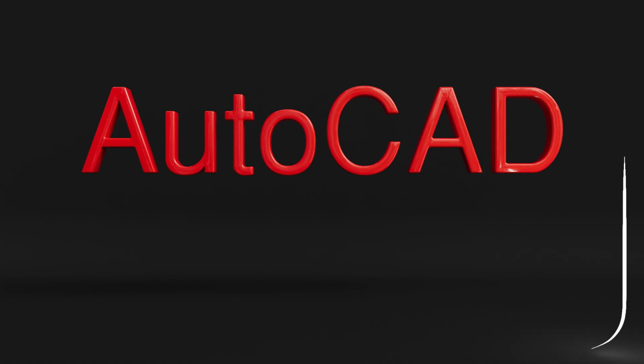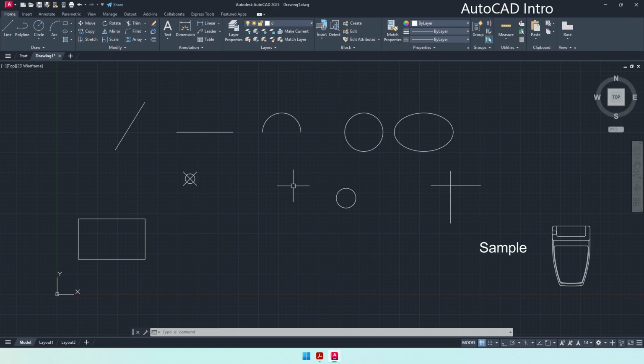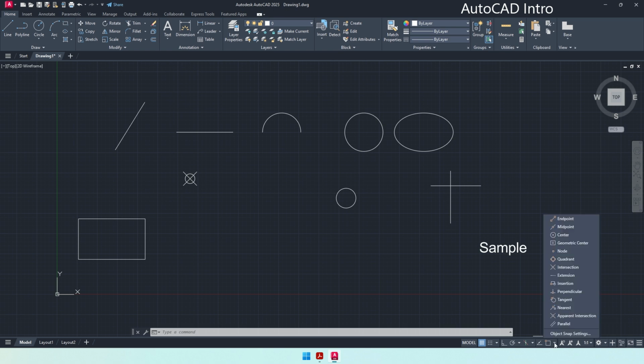Hi, I'm Ricardo, and today I'll be using AutoCAD to show you the different settings of the snapping tool. I'm going to use this drawing to show you all the different ways you can snap to an object. The snapping tool can be found down here, and if you click the little triangle next to it on the right hand side, you can then see all the points you can snap from and to.